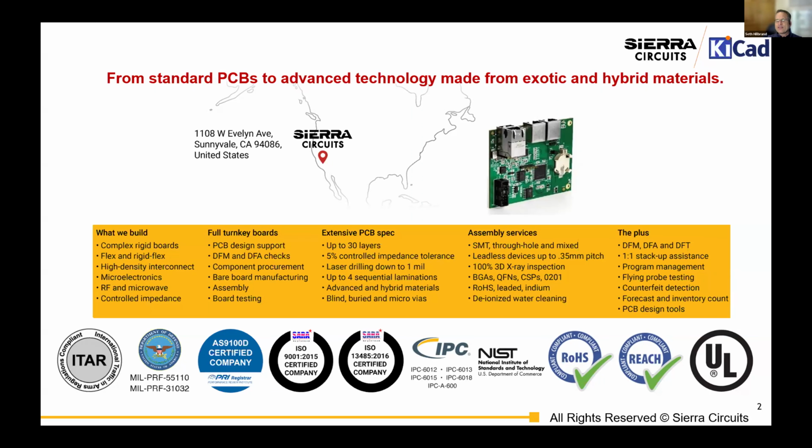But in this case, what the designer wanted was the ability to attach an element to the backside of the board and have it soldered on the front side, but not have any copper exist on the backside. They were designing a single layer board, so they did not have any plated through holes, so that wasn't a process that they were working on.